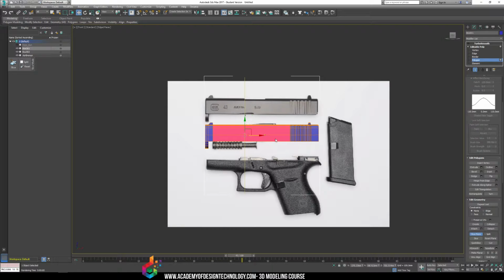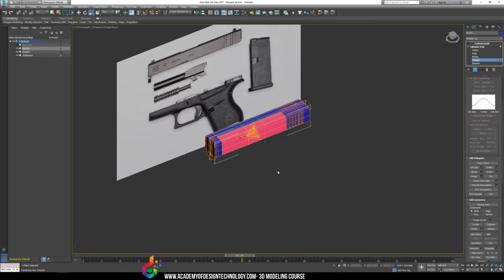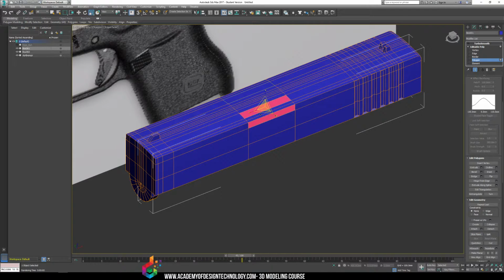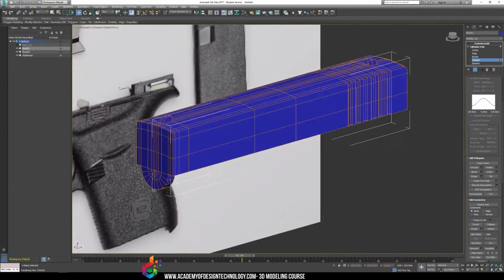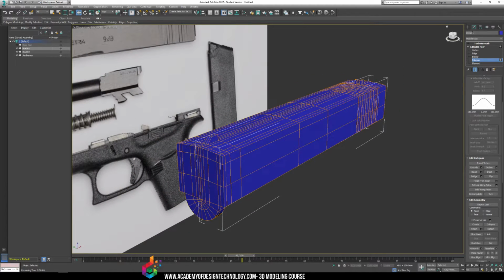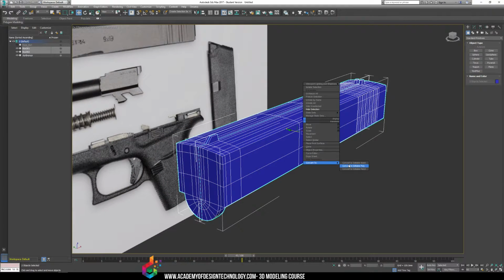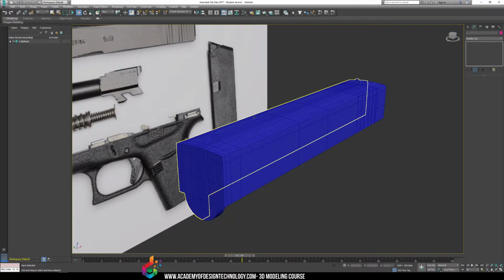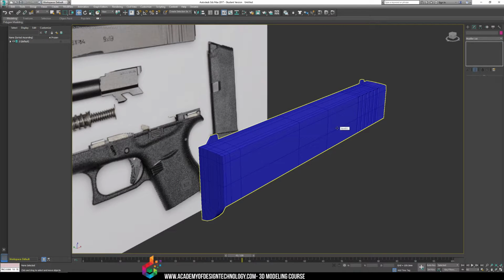You slice plane, sure, like you normally do. But we're not going to make the actual shape of the whole exit hole for the bullets to come out of, because if we do, it's going to appear on both sides of the gun. So what we want to do when we get to this point, and let's say we're finished and we're about to boolean the holes out and we're about to put the ejector hole, is we grab both parts of the model, we convert to edit poly,